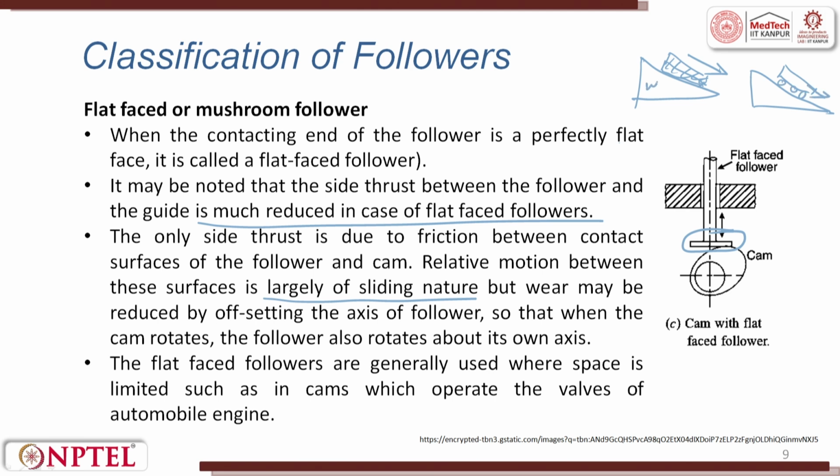So, this is the wedge. Here we are talking about sliding nature, but wear may be reduced by offsetting the axis of the follower, so that when the cam rotates, the follower also rotates about its own axis. It can rotate like this also.